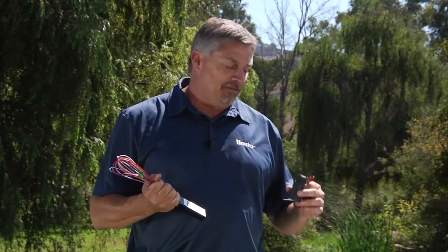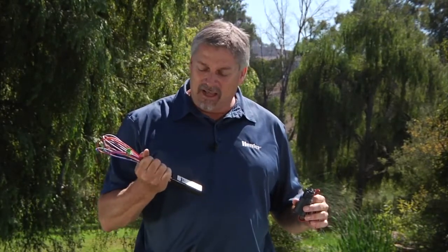Likewise, be sure to connect the extended wire coming from the black wire to the black terminal at the controller. If you plan to connect your Hunter FlowSync flow sensor through a sensor decoder, the same concept applies with respect to polarity. Also, be sure to program your sensor decoder at the controller before you install it in the field.